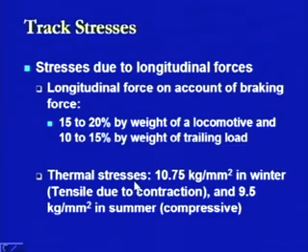When this expansion or contraction of the rail section is restricted because of the fastenings provided between the rail section and the sleeper, it induces thermal stresses. When these thermal stresses are induced, they create a problem at the fastening levels. That is why the fastening needs to take these stresses into consideration, and this is defined in terms of either winter or summer conditions, because we have two different types of behavior or nature of stresses induced in any section.